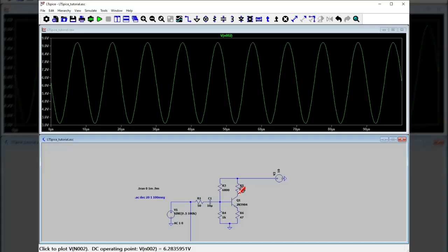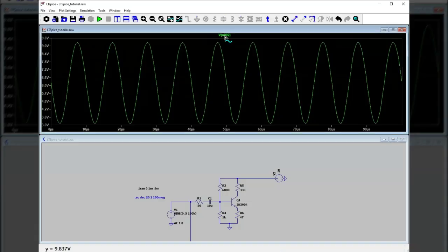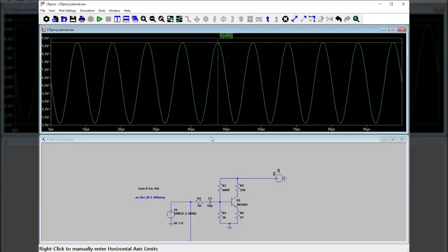You can see exactly what the waveform looks like and what the voltage swing is, and what the maximum and the minimum are. And I think you can see here, in the little dialog box, which you can't see, peak voltage is 9.3. So we only have 0.7 of a volt before we get to our supply rail, and we're kind of close to clipping, but we're not clipping.